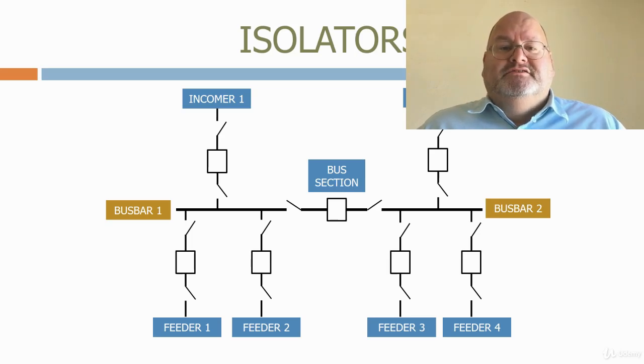For manual isolators, additional force can be used to prise it open. But for motorized isolators, this seizure may result in the main motor tripping. For isolators that are used all the time, this can cause wear to the contacts, especially when they are continually breaking or making magnetization currents. This may result in the contacts having to be replaced after a certain amount of operations.